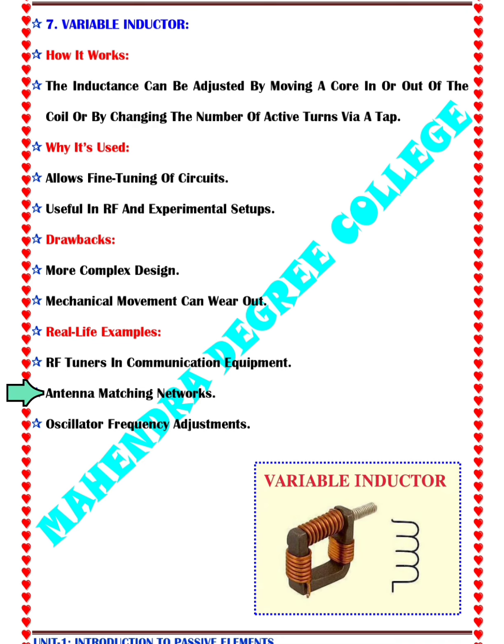Antenna matching networks. It means helps match the impedance of the antenna to the transmitter or receiver for maximum power transfer. The variable inductor allows tuning for different frequencies or changing environmental conditions.